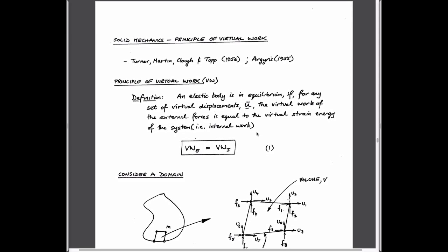Okay, so let's start talking about the solid mechanics part. We could derive the solid mechanics part in terms of a conservation equation, which is conservation of momentum. If we don't look at the dynamic case that includes inertia, then those equations become what are called the equilibrium equations. And so we could derive the behavior from the stress equilibrium equations. But actually, I think it's much easier to derive them from this principle of virtual work, which is equivalent to the equilibrium equations.